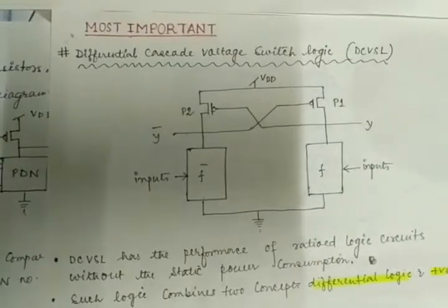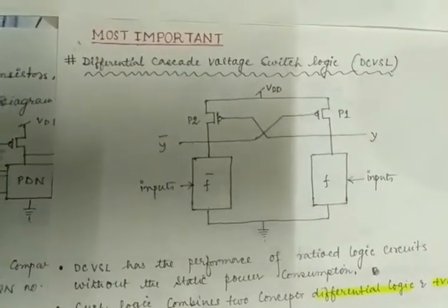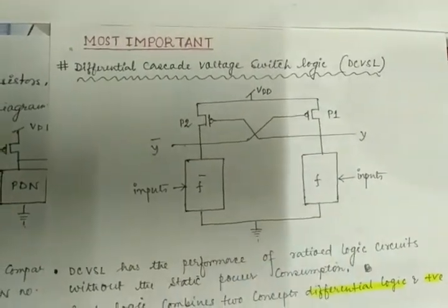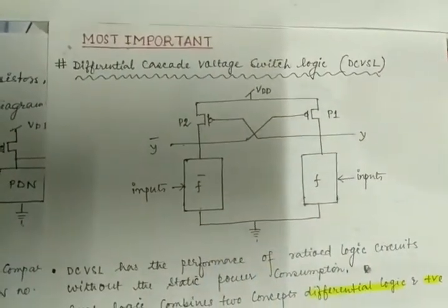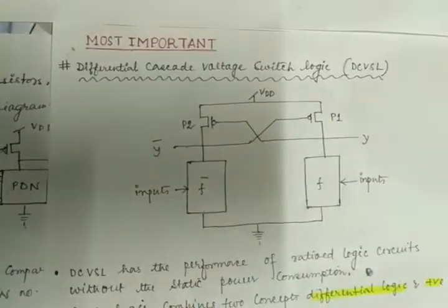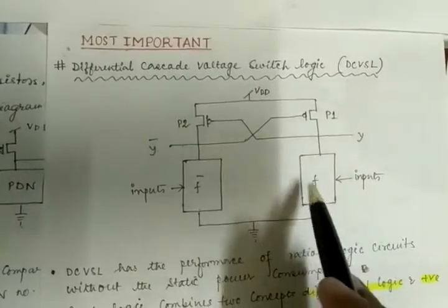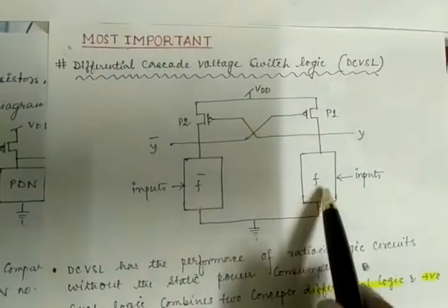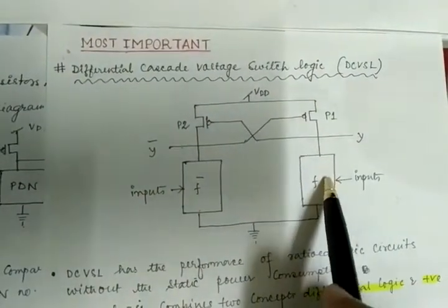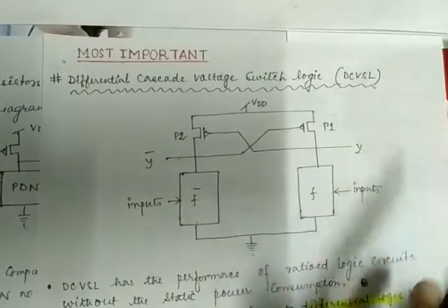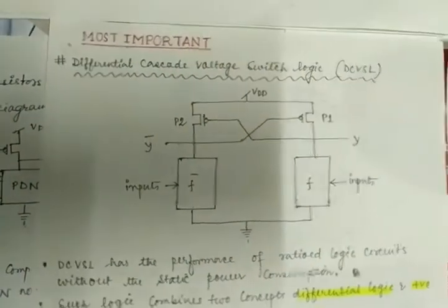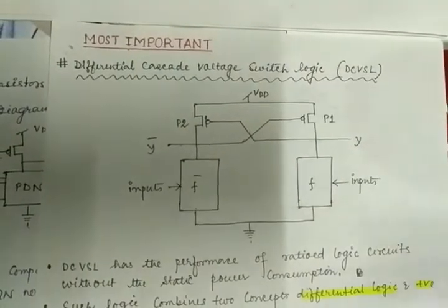Right? Okay, so let's see how it will function. So assume that you are giving the inputs over here. Such kind of input that F is on, that means you are giving high input, means 1. So F is on because this is designed with NMOS. So if F is on, then this is the output associated with that. What value will we obtain? The obtained value is 0. Yes, because this NMOS transistor is conducting. So Y is equal to 0.